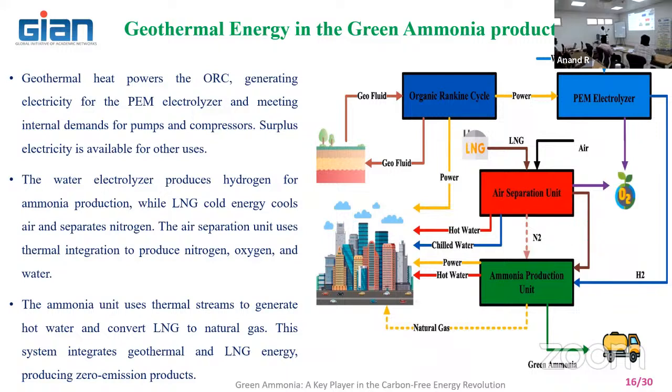In the same way, you put a drill under the earth, find the molten lava at a particular point, and inject the water at that point. When you inject water into the high temperature, high pressure zone underneath the earth, superheated steam comes out. That steam is utilized for power generation, like a conventional steam power plant. Or if the heat potential is less, you can go for an organic Rankine cycle, where you replace the water with a low temperature fluid that can be used for producing power. The other things remain the same.